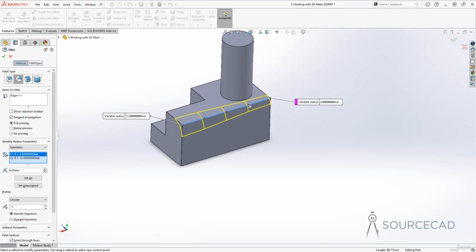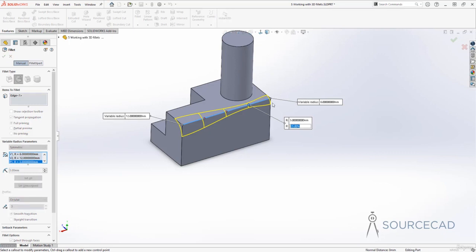So in this case, I'll maybe make this radius smaller. So I'll just click on this point, and now we have radius and percentage value. In the radius, I'll click and I'll change that to 3 and enter. Now it's very small. The percentage value is actually the percent distance. So this is at 0% and this is at 100%. So if you want to move it closer to this point, decrease this value. If you want to move it further away from that point, increase this value. So maybe I'll just make it 32%, and I can see it will move further away from that point.